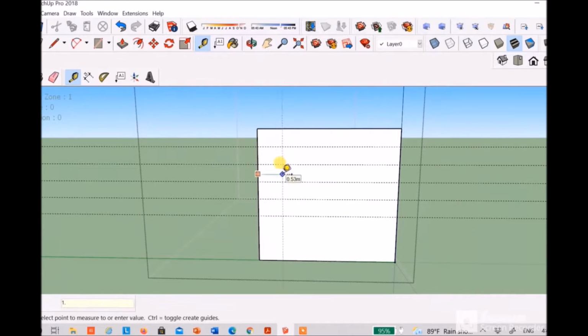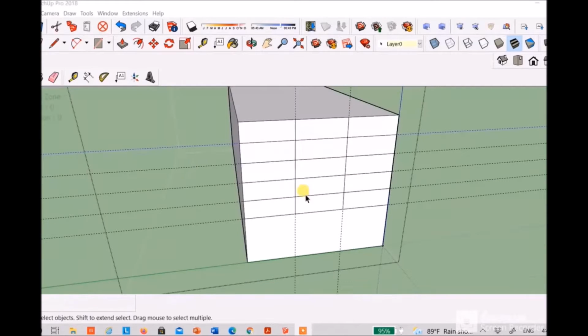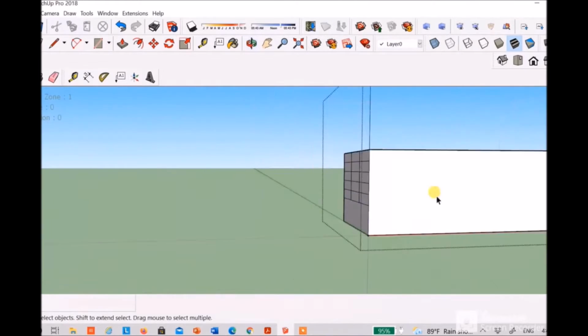and we make 3 vertical divisions of 1 meter each. Next we select the line option from the toolbar and we create edges between the endpoints both horizontally and vertically. We can now select and delete the extra lines that we used to create these subsections. Next we proceed to another side of the model.